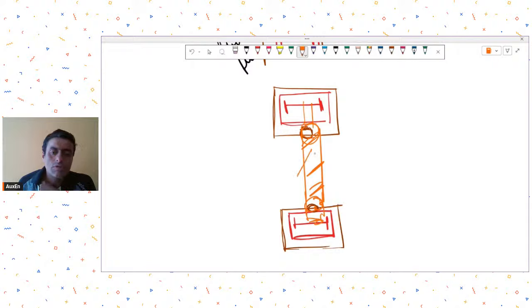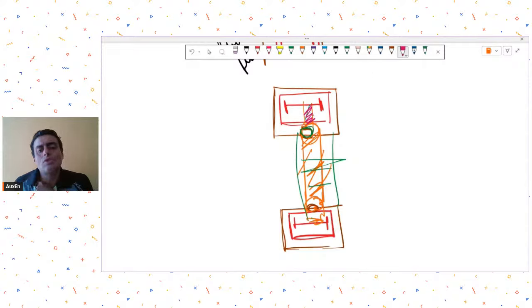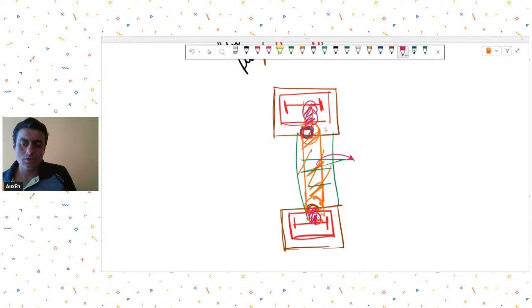So this portion of the brick wall, and of course there will be a ground beam or whatever below, is just connected with the mullion column, and then this small brick wall you can construct later on. So even if cracking, lagging, etc. has to happen, it will happen on these small little portions. You will not see any significant issues with the main wall. So what I have done, I have isolated my main brick wall by providing mullion columns on either side. So this can be one of the options you could think of.